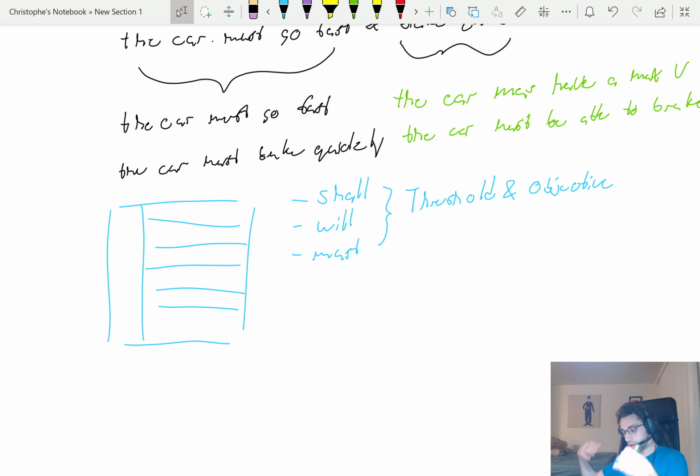Once you get this list of single statement, verifiable, and clear requirements from your customer, you're going to start looking through these for commonalities. So you're going to start grouping them and saying, oh, these requirements are kind of similar. These requirements kind of pertain to something like the attitude, direction, and control systems, ADCS, on a satellite. Oh, these ones kind of pertain to energy and power systems. Start grouping them up into different allocations.